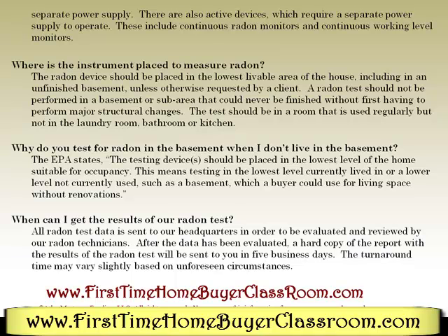Where is the instrument placed to measure radon? The radon devices should be placed in the lowest livable area of the house, including an unfinished basement, unless otherwise requested by a client. A radon test should not be performed in a basement or sub-area that could never be finished without first having to perform major structural changes. The test should be done in a room that is used regularly, but not in the laundry room, bathroom, or kitchen.